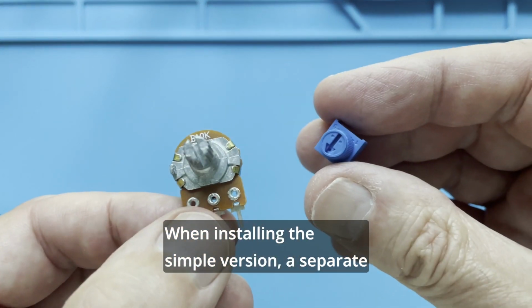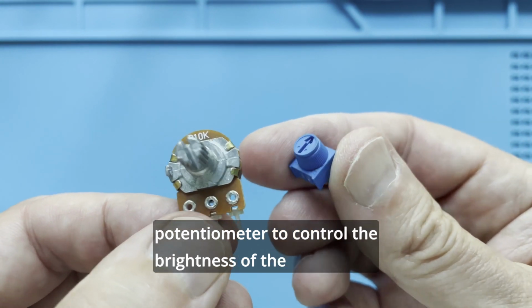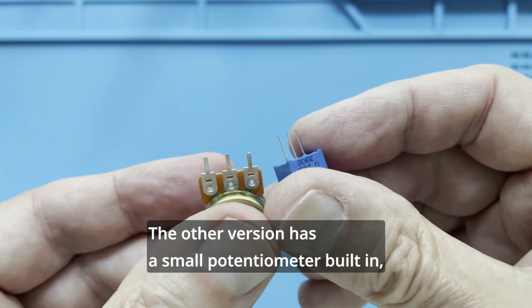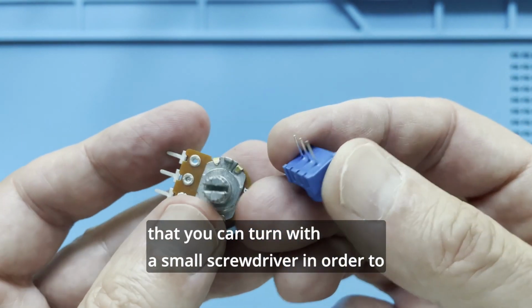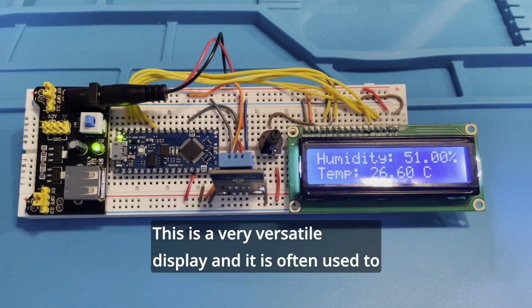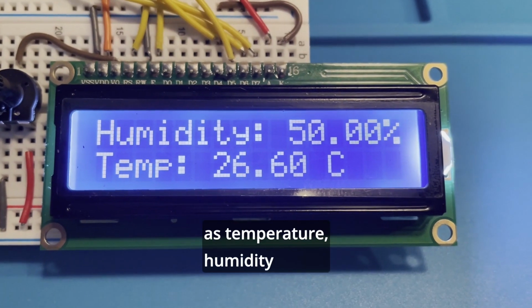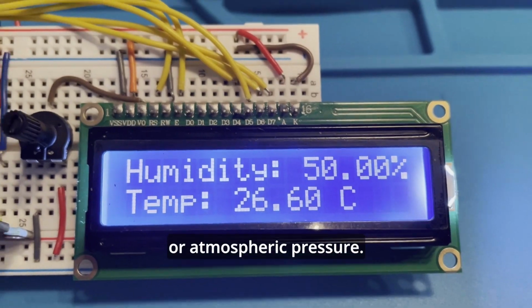When installing the simple version, a separate potentiometer to control the brightness of the display is needed. The other version has a small potentiometer built in that you can turn with a small screwdriver in order to adjust the LCD. This is a very versatile display, and it is often used to display the readings of measurements such as temperature, humidity, or atmospheric pressure.